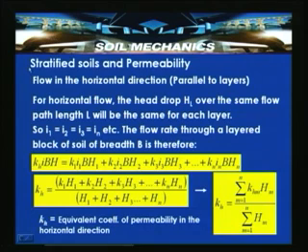That means all layers will have the same head loss, because horizontally, though the layers are stratified, the same head drives the flow from the left side to the right-hand side. So, let us look into how the flow in the horizontal direction, parallel to the layers, can be obtained. For horizontal flow, the head drop HL over the same flow path length L will be the same for each layer.